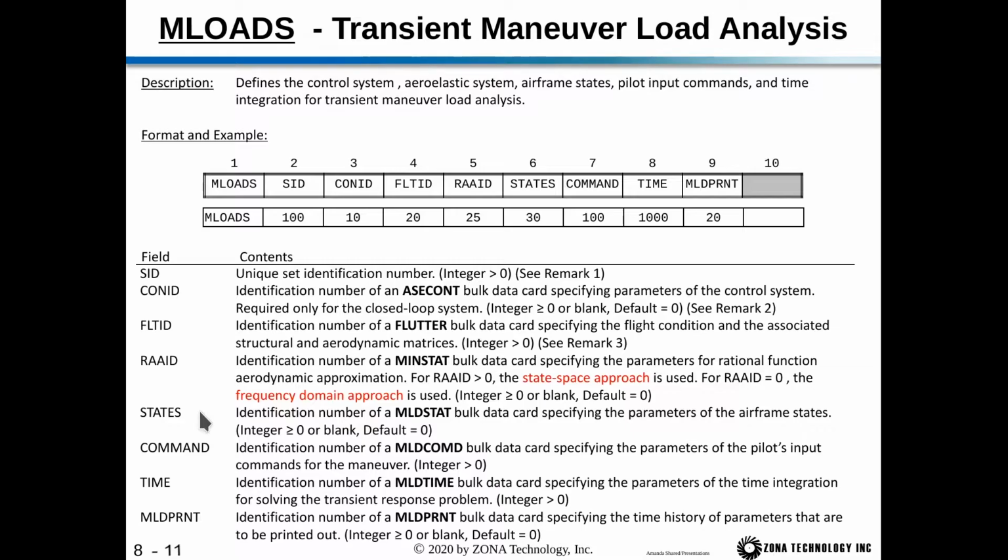The states field refers to the MLDSTAT card, which allows you to specify the airframe states. The command field refers to the MLD command card, specifying the pilot input. The time field refers to the MLDTIM card, specifying parameters of time integration. And then lastly, the MLDPRINT field refers to the MLDPRINT card, which allows you to output a time history of parameters of interest.